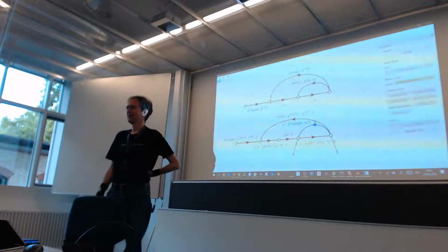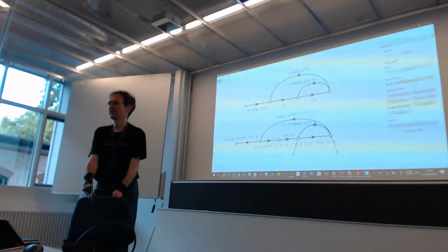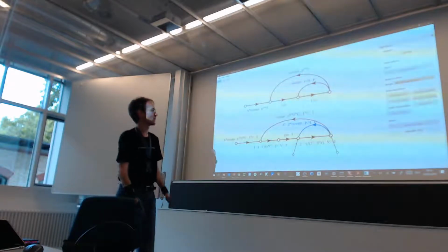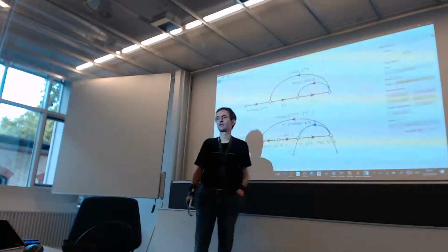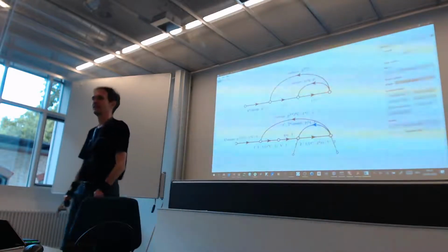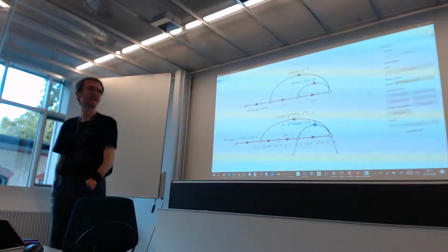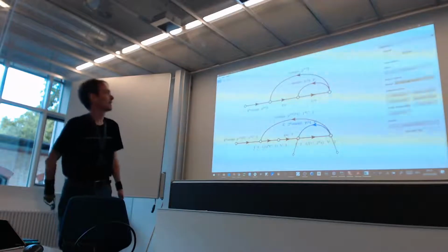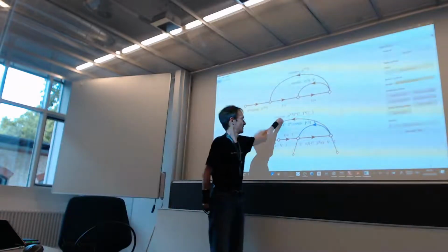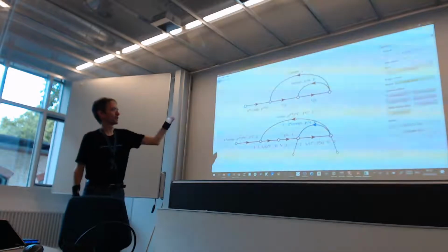And just like this here, it doesn't really look very much like a transconductance, but if you think about the units, here I have a capacitance times angular frequency divided by something without a unit. So indeed the unit of this is Siemens, farad times radian per second. So this is a transconductance. Also, that one here is a transconductance, which you have at the top.